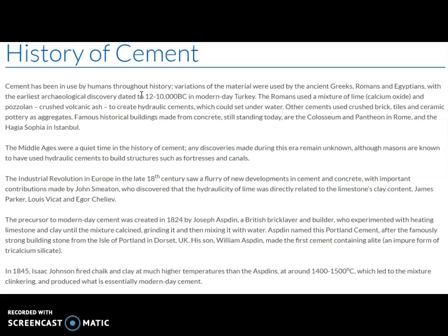That's calcium oxide that we studied now in the previous lecture. Okay, and this lime was mixed with volcanic ash. Crushed volcanic ash. This is called pozzolanic. People must have heard of pozzolanic cement. Okay, so lime mixed with this volcanic ash was used as cementitious material. So this was a hydraulic cement which would set under water.